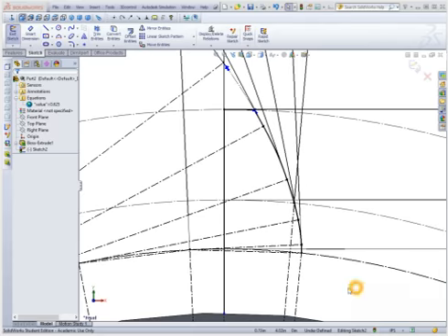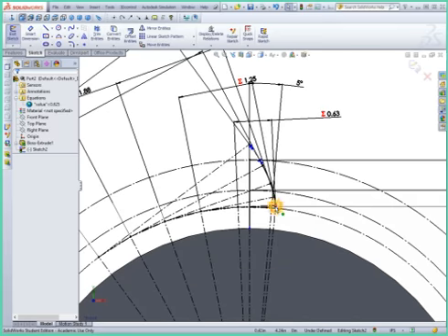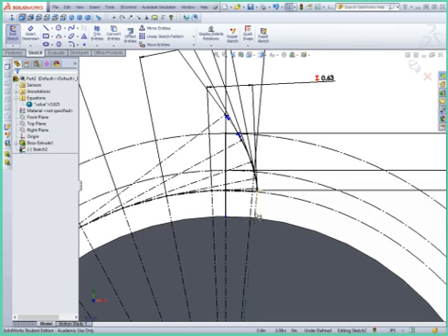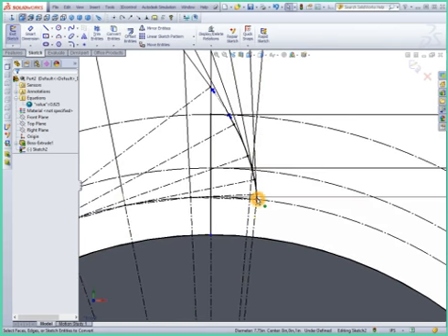The last thing we have to figure out now is how the end of the tooth connects with the rest of the gear system. We have our clearance down here on the dedendum, but there has to be some type of connection between here and there. I can fill in the bottom half using the convert entities feature, and we can trim off all that later. But we have to have some transition from here to there. We could just follow this straight line, but that probably wouldn't be a very strong tooth profile.